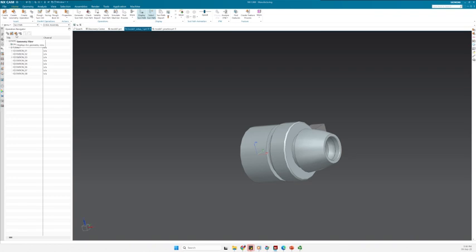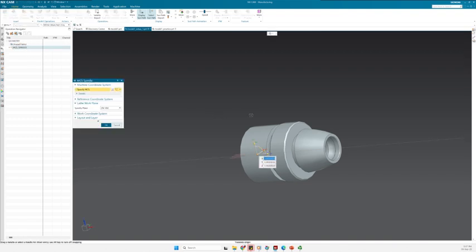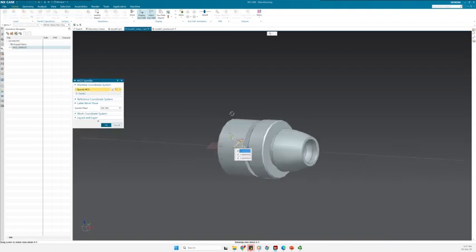In the next step, we go to the geometry view. In the geometry view are the steps where we are going to define the parts, blanks, any avoidance, and so on. We will come back to it. And we have the machining method view. The machining method view holds the operations that we are defining: the roughing, finishing, drilling, groove, thread, and so on. So we go back now to the geometry view. In the geometry view, I can just double click on the spindle, the machine coordinate system spindle, and this is the first thing you need to check very carefully.